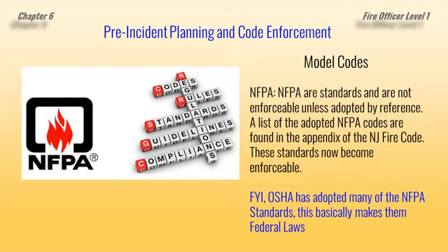Now, if you read some of the NFPA standards for fire department operations, they're going to tell you that one of the first or second units responding to a fire in a building that has a sprinkler system is to have one of those engine companies hook up and supply the sprinkler system. And there's been fire departments who've been sued based on that NFPA standard where they neglected to put water into the sprinkler system and the building was a total loss.